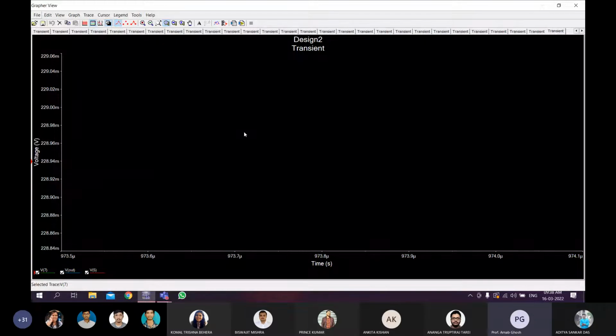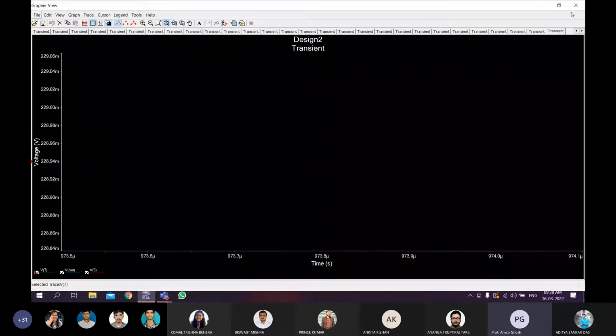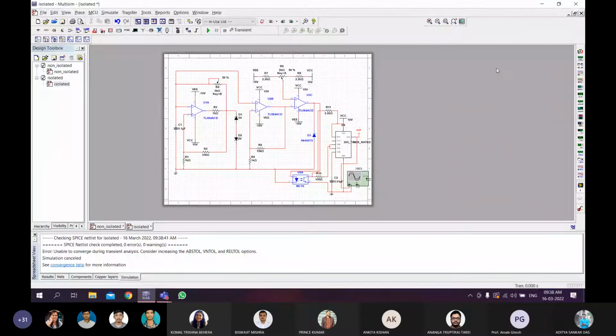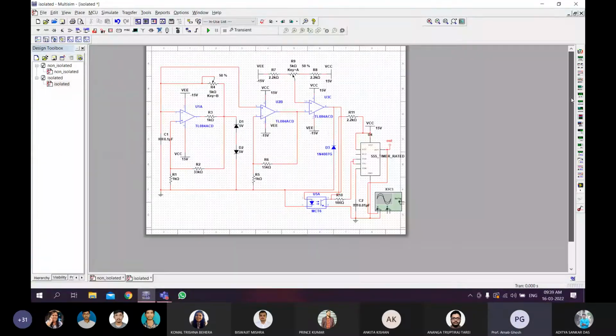You made some mistake. I think there is a biasing voltage polarity problem. Maybe you connected VCC with minus voltage. Maybe you need to check it. Okay, sir.